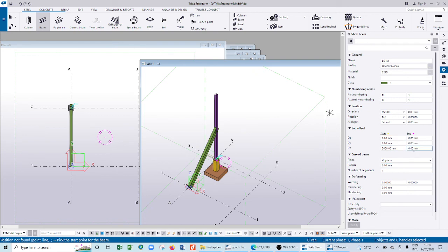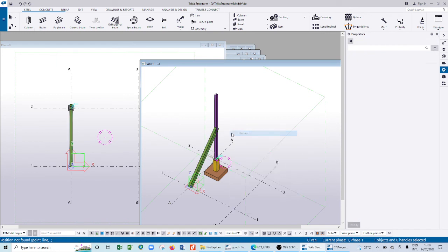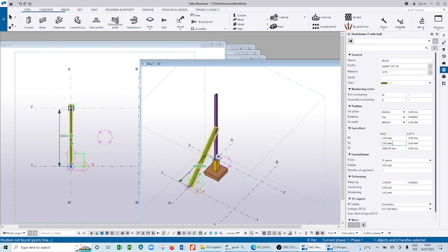So meaning when you change also on this other, this is on the Z, change it to 3,000. Press on this, escape, interact. Then you click on this beam. I want this end part because this is the starting part. If you are saying it, this is the ending part.